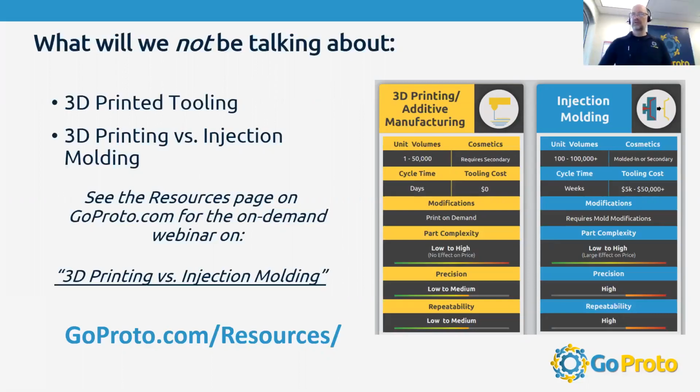Yeah, I guess just a little bit. These are certainly things we do, 3D printing tooling, maybe 3D printing of some of the components. That's an important area that we are focusing on, and several of the questions were around that. At this point in the world, it is certainly a viable technology to 3D print parts of it. We generally are focusing as a business on very fast but predictable machining and EDMing of metal blocks to create your injection mold tooling. The reason is, it's dependable, it is predictable, and it also is something that we can do extremely quickly and at low cost.